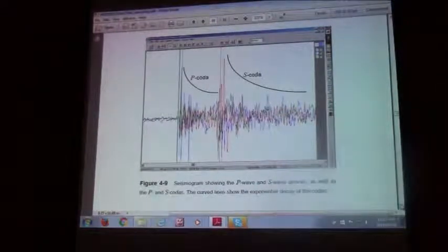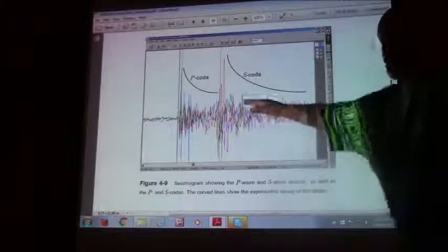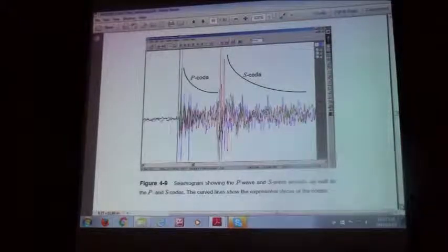Okay, and on the one hand, this is just energy that's been bounced around from excavations and other kinds of reflectors. And this is useful when we are trying to characterize our rock mass. What we're trying to do in mine seismology is to see how your rock mass is changing as mining proceeds, and if there are signals that can indicate that it's starting to get damaged and a big seismic event could occur.